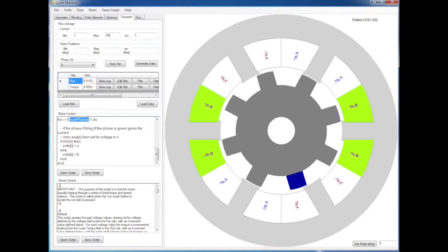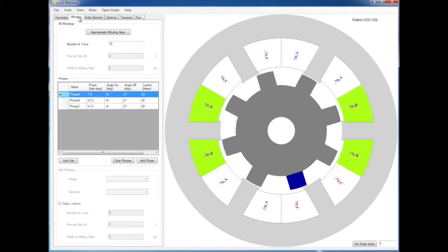If you look down here, there's this statement right here, this if is on. Is on is a function that I provide. This is a function that I wrote. You basically just give it an integer, some value between 0 and num phases minus 1. What it does is it looks at your winding table, and it determines, given the current angle of my rotor, is that phase on?